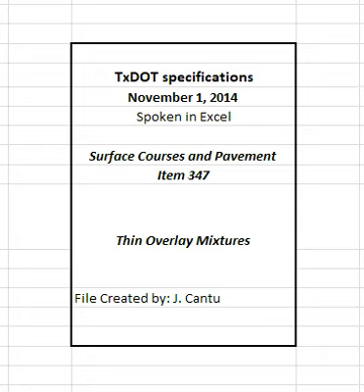Use tamps to thoroughly compact the edges of the pavement along curbs, headers, and similar structures and in locations that will not allow thorough compaction with rollers. The engineer may require rolling with a trench roller on widened areas, in trenches, and in other limited areas. Use Tex 246F to measure water flow to verify the mixture is adequately compacted. Measure the water flow once per sublot at locations directed by the engineer.